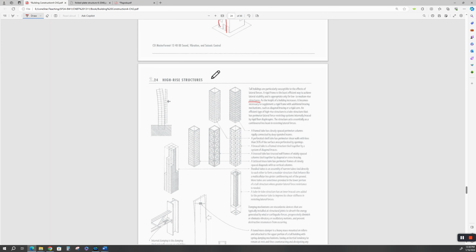So if you had a pan floor and it was reinforced concrete, you could use that as a diaphragm. And they're called diaphragm floors, and they work as a giant shear panel. So if you have a square building and each one of these major floors was a diaphragm, what have you essentially done? You've stiffened your building up, right?